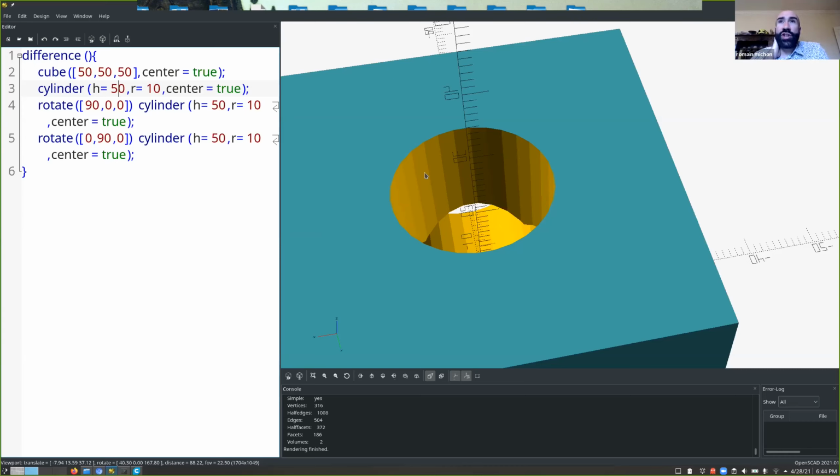The reason is that OpenSCAD generates STL files, which are basically a set of Cartesian coordinates in a space. It says, there is a node here, there is a node here, in our X, Y, Z space. But it's not a vectorial 2D object where you say, here I have a circle and the diameter of the circle is that. When you generate an STL file, in the end, it's just a set of Cartesian coordinates. And because of that, whenever you make a circle, you can only make it out of flat surfaces, and there is nothing you can do about that.